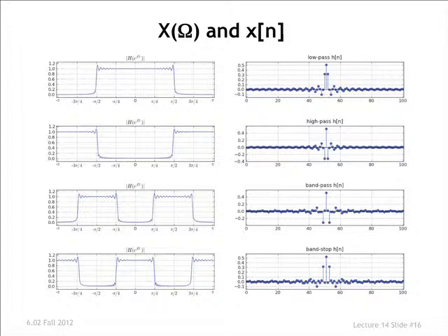All right? Here's another signal whose spectral content is at high frequencies and essentially zero in the low frequency range. What does it look like in the time domain? Well, you can actually work it out. And here's what you see, that this has actually more wiggle to it than the sinc does. Alternate samples seem to take opposite signs, at least of the dominant ones over here, reflecting the high frequency content of that signal.